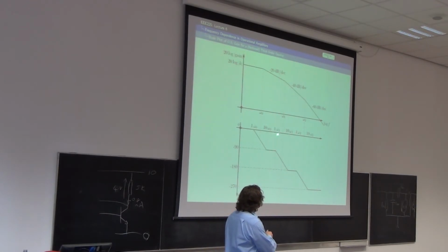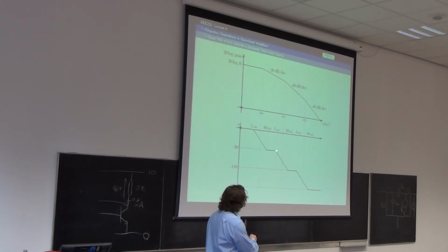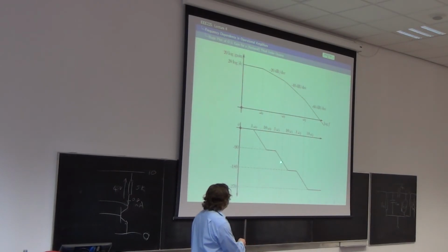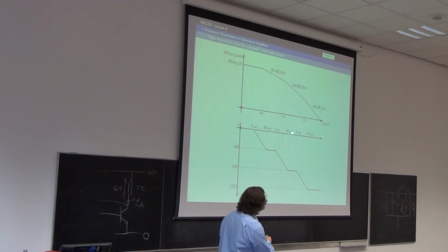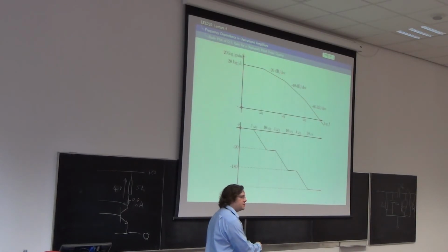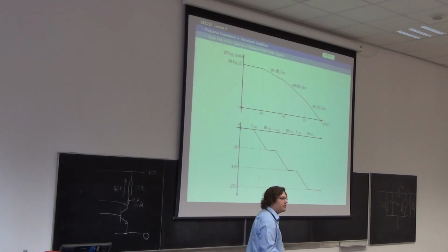When I get to about 0.1 times the second pole frequency, I will start to feel the effects of the phase shift due to this pole, and by the time I get to the pole frequency, I'll have another 45 degrees on top of the 90 that I already had. And by the time I'm 10 times higher in frequency than the pole frequency, I'll feel the effects of the full 90 degrees of phase shift that this pole's going to give me. So then I'll be down to 180. And similar arguments for the last one. Happy with that or no?